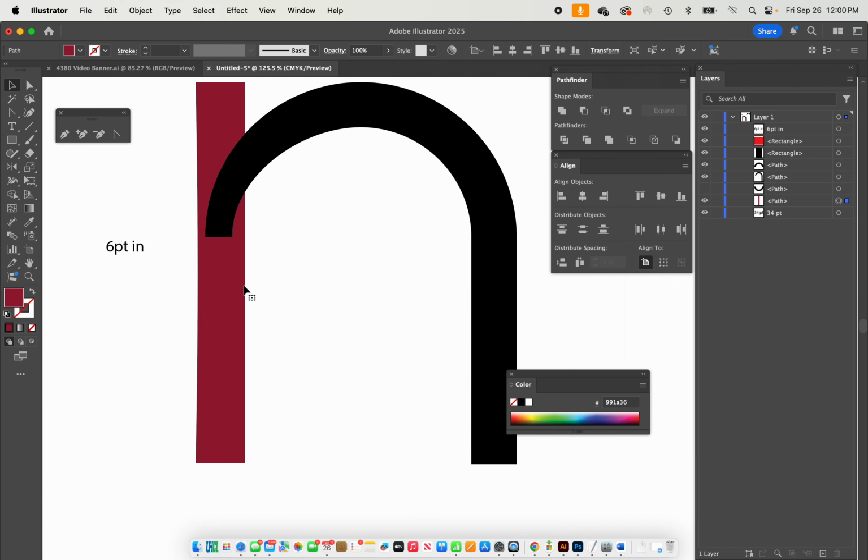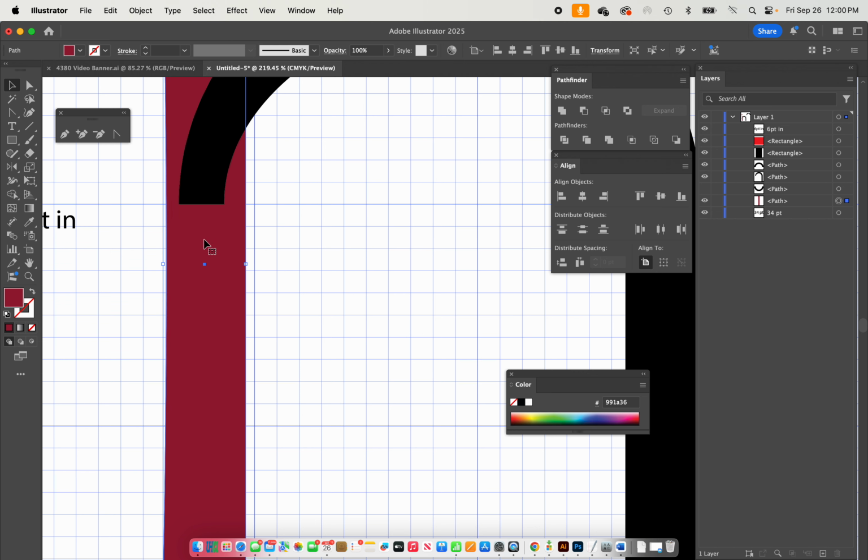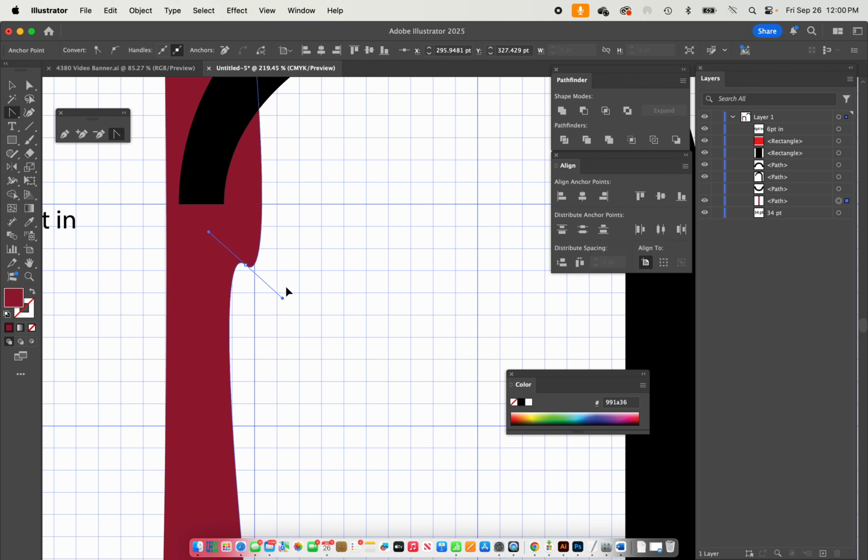We might want to do the same thing to the other side. So, more quickly, select the shape, get the plus pen tool, click on the line, get the convert anchor point, press and hold it down, make sure we're going in the proper direction, hold the shift key down to do that, get the white arrow, make sure only that one point is selected, and we're going to go in 1, 2, 3, 4, 5, 6.